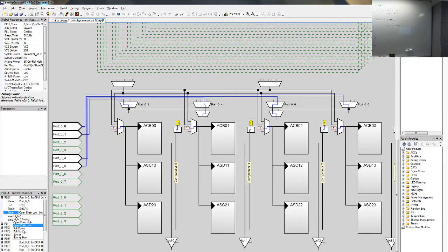In this kind of case, you don't need the external resistor. You can use the pull down resistor, which keeps the signal on ground unless there's a voltage coming in. Okay. Pull up and pull down are used for inputs, especially digital inputs.